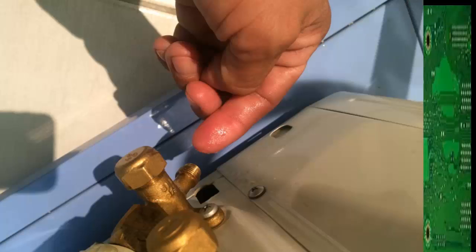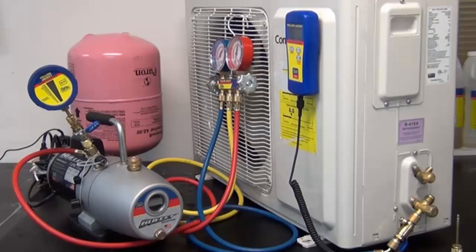9. Review of excess or lack of refrigerant. A unit with a higher amount of refrigerant has excessive current consumption, generating the H3 error. Even a unit with a refrigerant deficit may, in some cases, have an abnormal gas temperature, specifically at the compressor discharge, causing the H3 code.